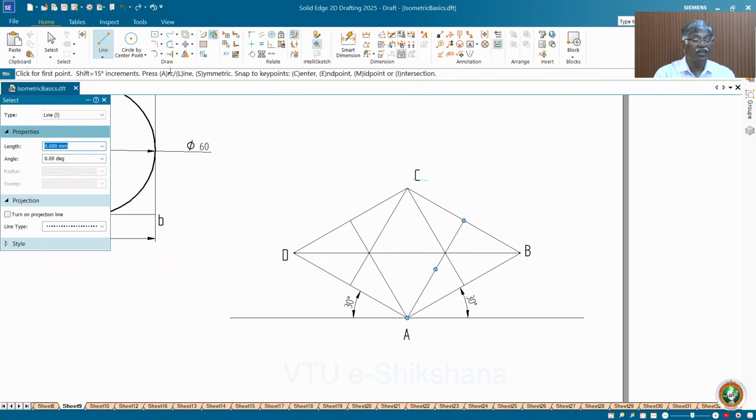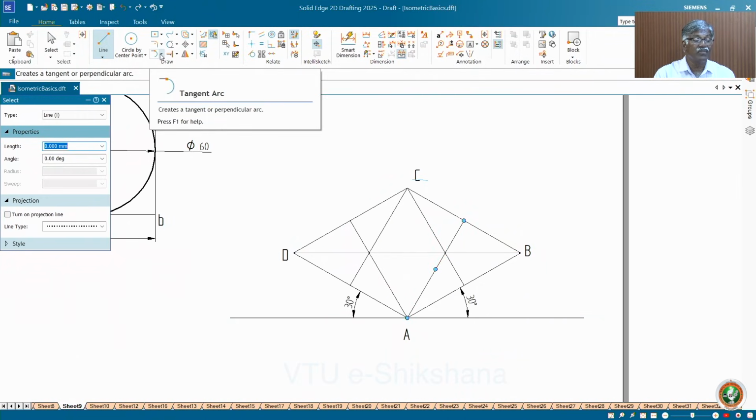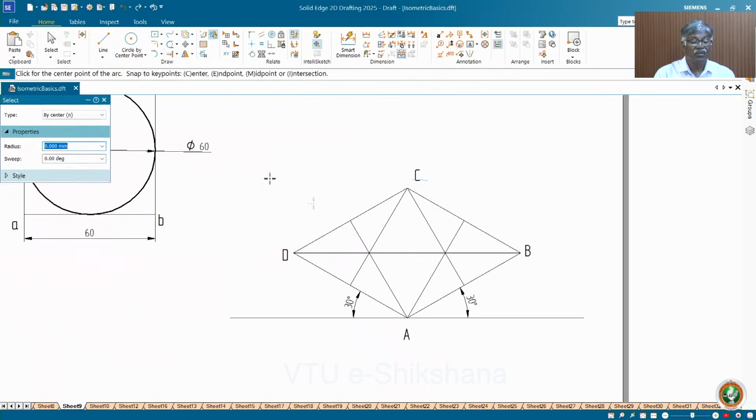Now you take this arc method, arc, with one or two centers, draw arc. Two segments you can complete with this. See, yeah. Then with this as center, A as center, you need not name all the time. Just for reference, I am giving MN, PQ, etc. These two segments you can complete.